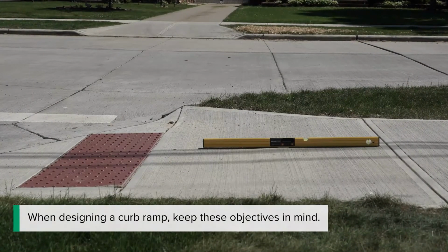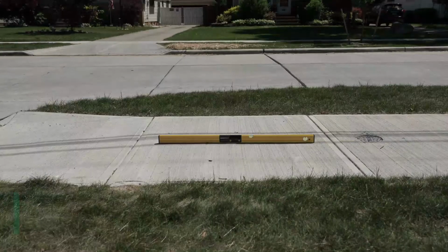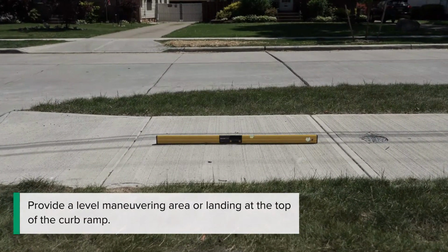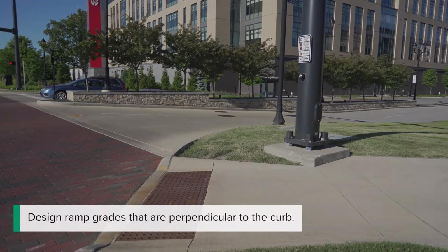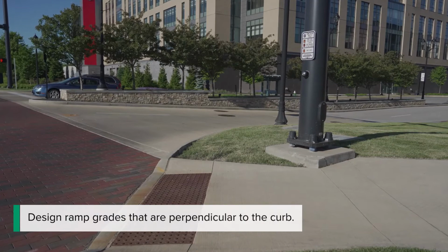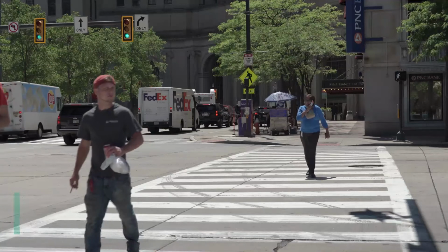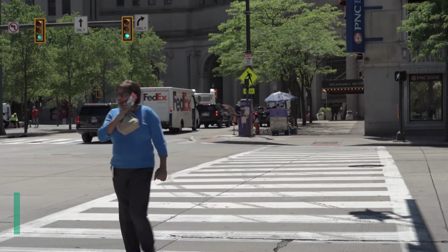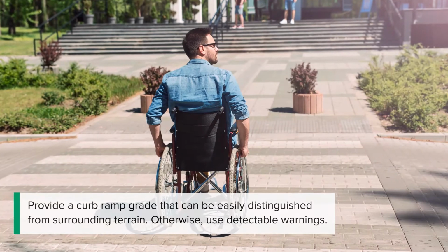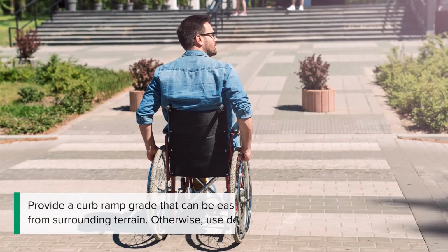When designing a curb ramp, keep these objectives in mind. Provide a level maneuvering area or landing at the top of the curb ramp. Design ramp grades that are perpendicular to the curb. Place the curb ramp within the marked crosswalk area. Design the ramp so it doesn't require turning or maneuvering on the ramp surface. Provide a curb ramp grade that can be easily distinguished from surrounding terrain. Otherwise, use detectable warnings.